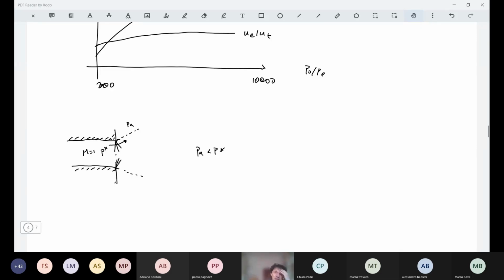But also in the planar case, what we can see is that here we have pressure waves coming from this side and also from this other side. So they interact with each other such that we actually have a signal, for instance here, linearized for simplification, that is an expansion signal saying that we should decrease the pressure, but pressure is fixed outside. So actually this expansion wave should be balanced by a compression wave. And to make this compression wave, we have to turn in the opposite direction.